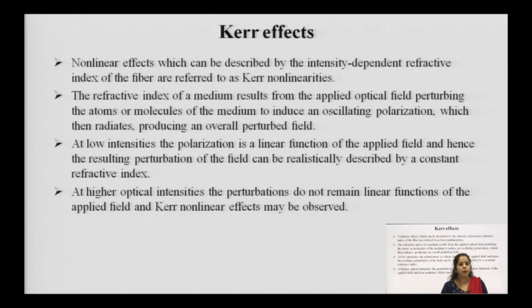Before proceeding further, let us have a recap of the attenuation section which we discussed in the earlier classes. We have gone through the different types of attenuation, which comprise the signal losses from the input end to the output end: bending, the absorption mechanism, and scattering.